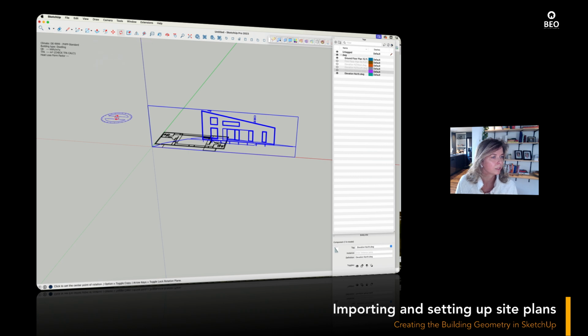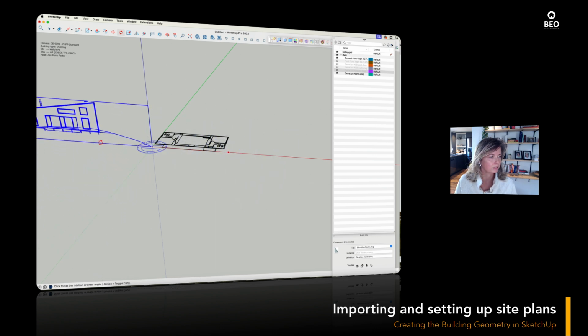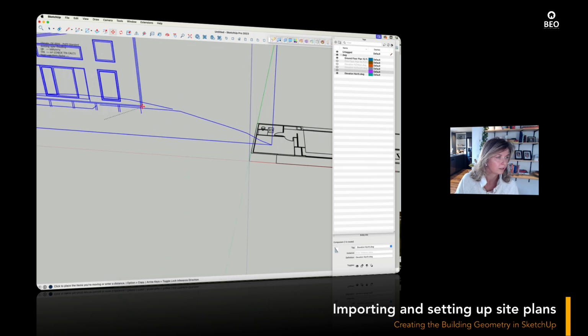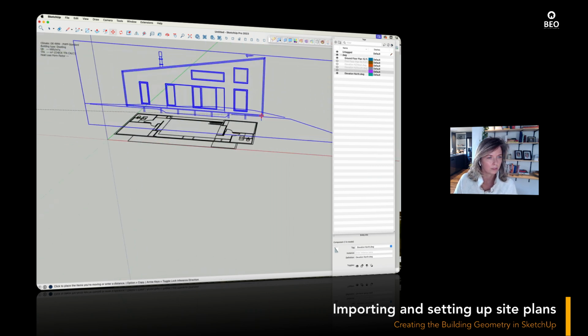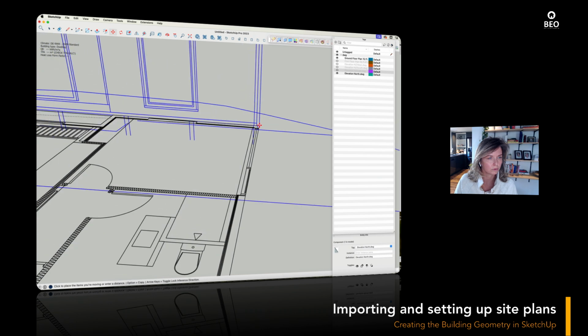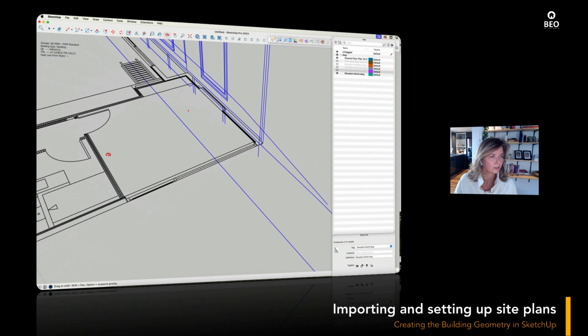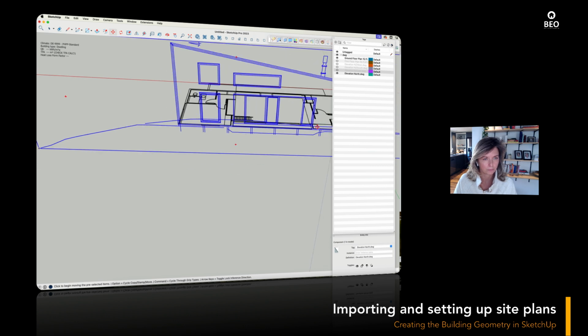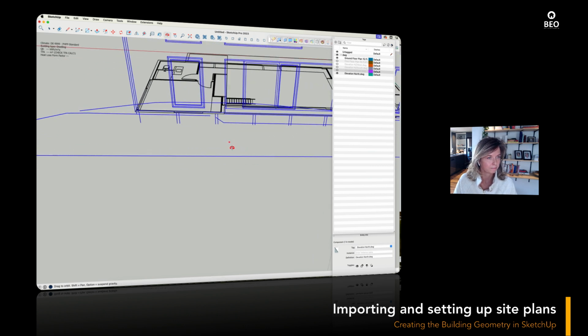So we're going to use the rotate tool again. This time we're using the blue orientation, and turn this around 180 degrees. And then from here I use the move tool and just select a corner here and put it on the corner here, and then I start aligning these drawings from here.